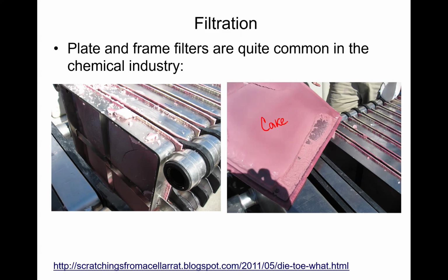So you have now here a filter with a fairly thick cake on it. Typically that filter is very porous, so it has a very small frictional loss along the filter itself. But the problem is the cake, because the cake will deposit very small particles. And when you deposit small particles over time, they get thicker and thicker, right? So that looks pretty much like a packed bed, but a packed bed that grows increasingly over time. At some point, this cake will be so thick that you can no longer pass liquid through, or the liquid flow is very small. And at that point, it's time to change your filter or clean your filter.